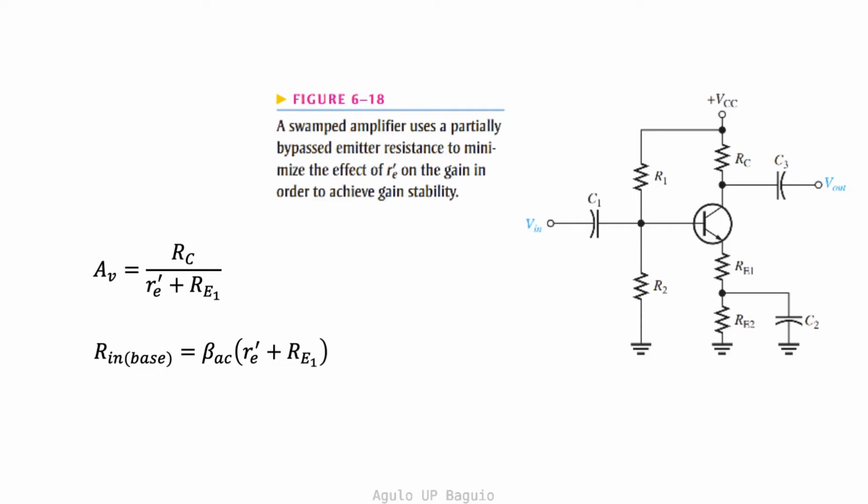There's one final note we need to discuss about the AC emitter resistance. The AC emitter resistance, as we've seen, is dependent on the DC emitter current. It is also dependent on temperature. Therefore, stability of the voltage gain is an issue. It is good practice to add a second emitter resistor at the emitter, just before the junction connecting the original emitter resistor and the bypass capacitor.